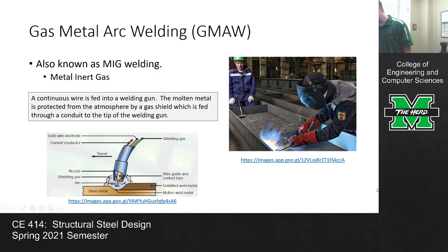Unrelated to welding, but on the picture to the right, what purpose do those plates sitting perpendicular to the web serve? That's a great question. Those are the plates that the welder is welding to this. If this is a beam, a flexural element, so think like shear and moment diagrams, those plates would stiffen the girder's resistance to shear, so that they increase the shear resistance.